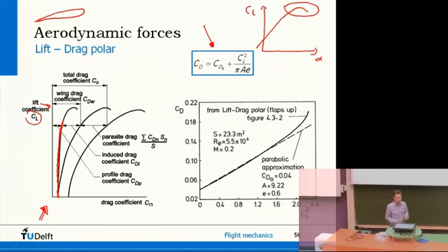But of course, I've just discussed that there's also a three-dimensional factor, that as soon as we start creating lift, we start losing energy in the atmosphere, and therefore aerodynamic drag increases. So if you just look purely at the wing, then if we're on the x-axis here and don't create lift, the drag would be the same as the two-dimensional case.